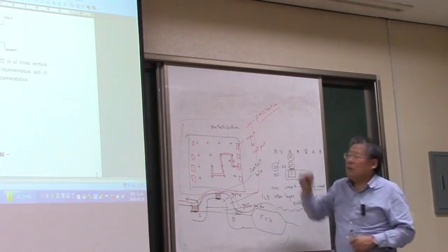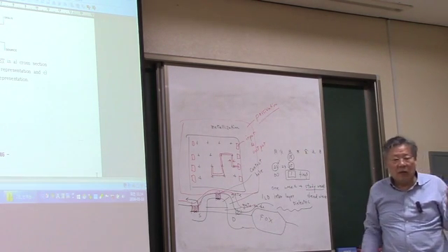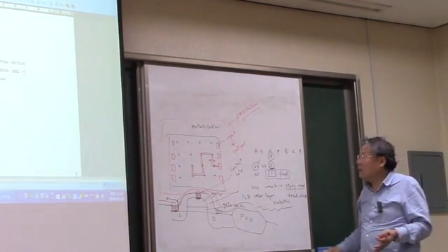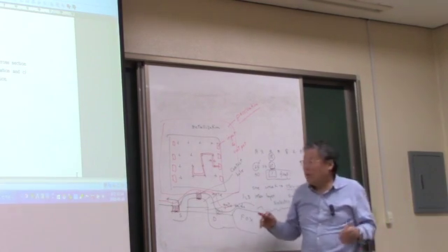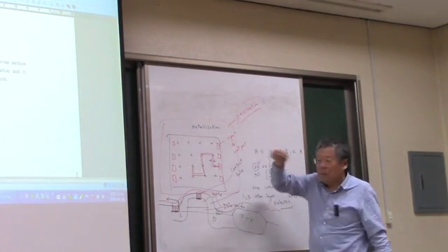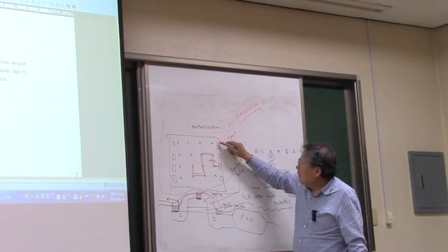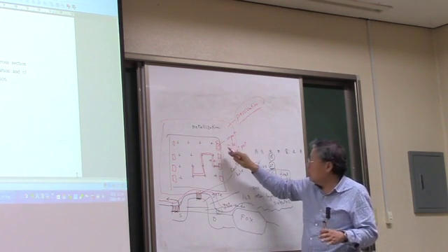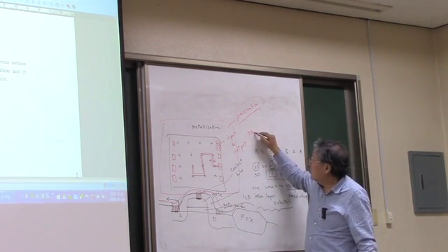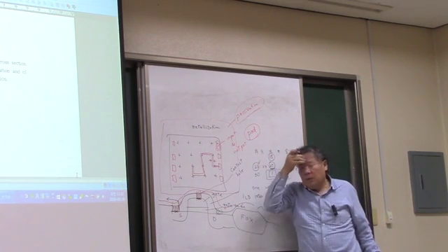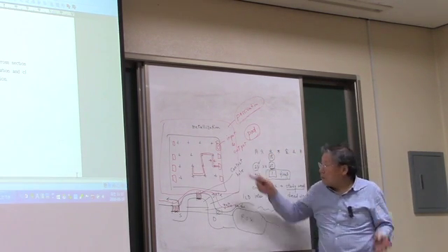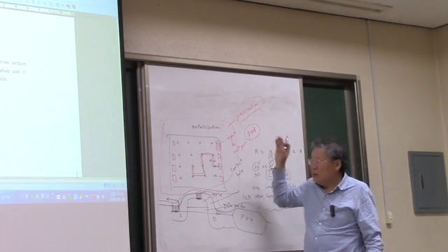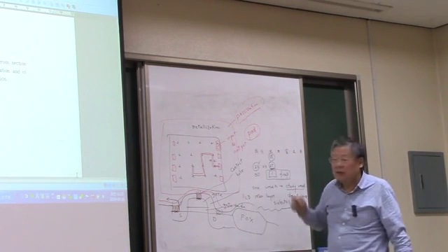We can do this with polymers, or we can use silicon oxide or silicon nitride, depending on the situation that we have. But we just do the passivation, and with the opening to this input, only this input and output pad is going to be revealed to air, and other areas are going to be all covered with this passivation layer.